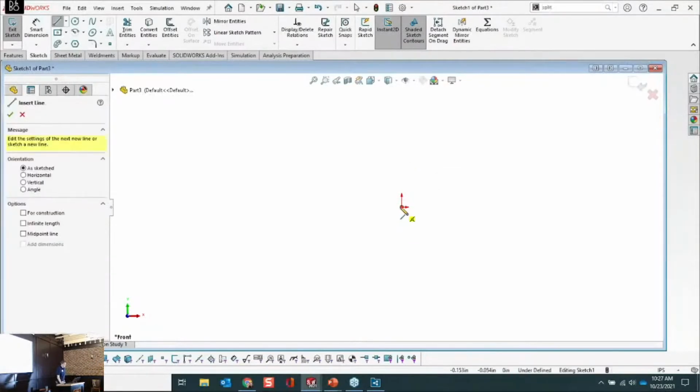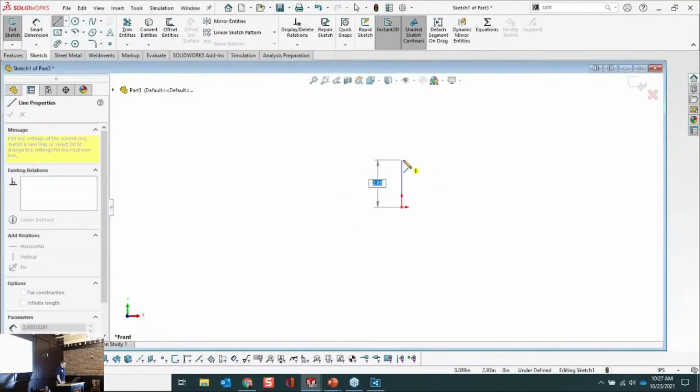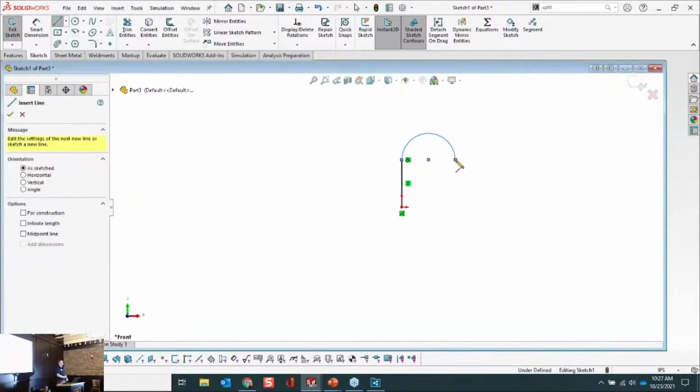So I'm going to start drawing a line. And the next thing I'm going to do is called the line to arc shortcut. So we know that if I single click again, it'll drop the line. Now, raise your hand if you didn't know that you can do this, but you can come back and rotate out and go straight into an arc. So a couple folks didn't know about that one. How much time did I just save you creating extra circles and trimming just by knowing that exists now?